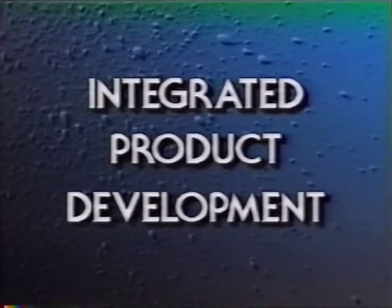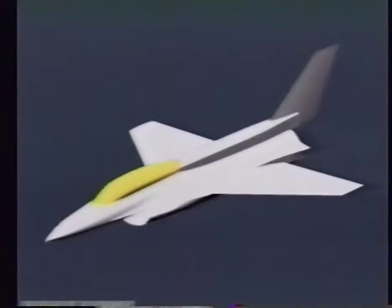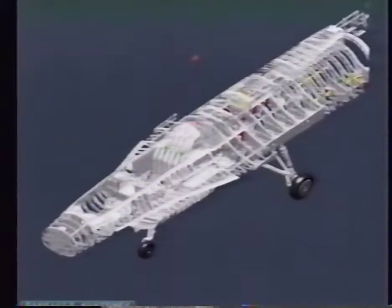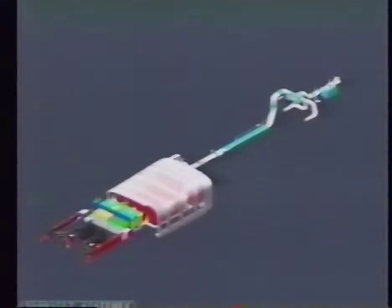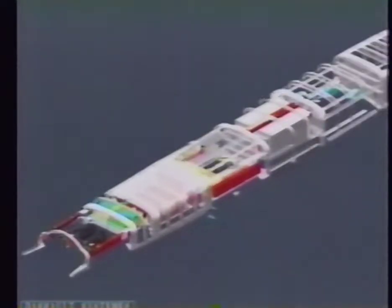The Vista airframe is a production F-16, modified to meet program specifications. Construction of models began with master dimensions database surfaces used to define the airframe envelope. From this database, primary and secondary structural parts were modeled and stored in a library from which zone models were created. The zone models depict all parts within a given area, such as the ammo drum bay or the conformal dorsal. These models define volumetric constraints and provide an interface for the design groups.